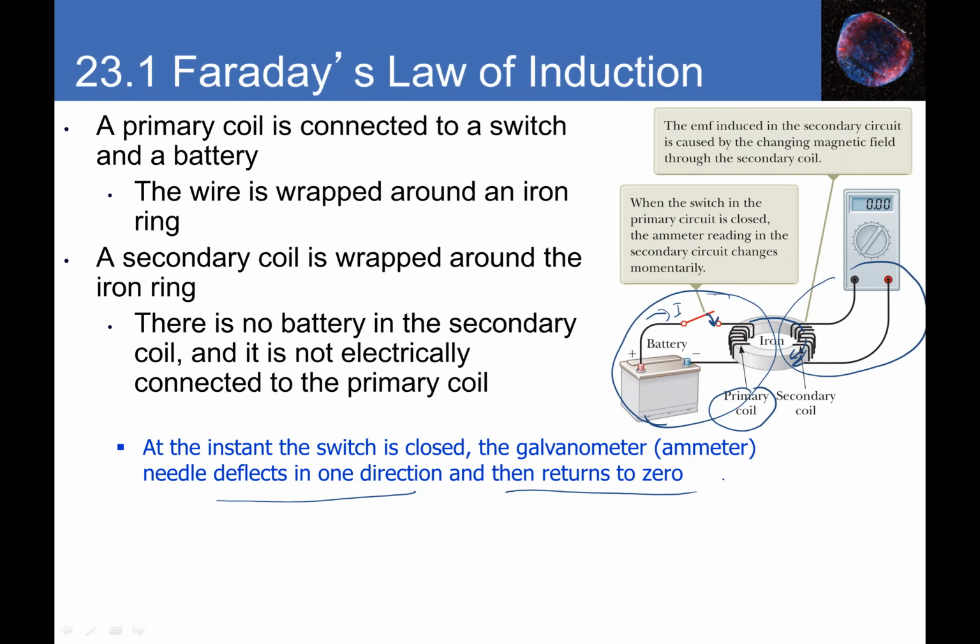Well, let's say we open the switch for the primary coil, so there is no current. Now when I close the switch, this current doesn't go to its maximum at t equals 0. What it does is slowly increase. Well, when I say slowly, the current over time, for the primary, happens maybe in milliseconds. So for us, it's very quick.